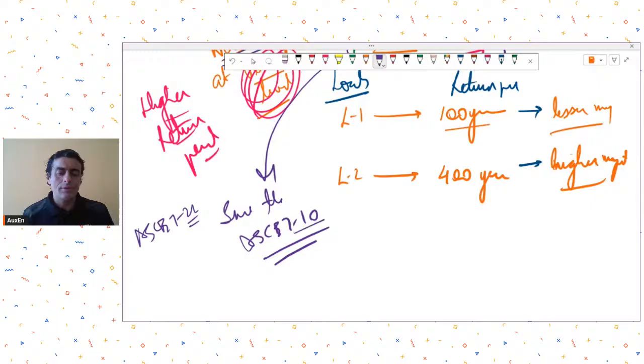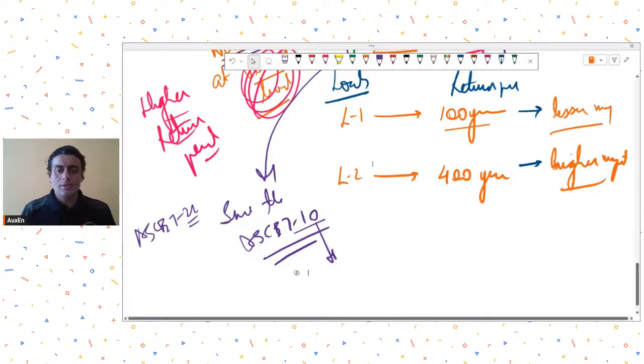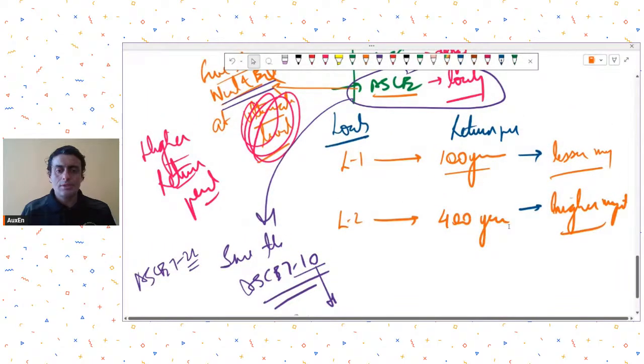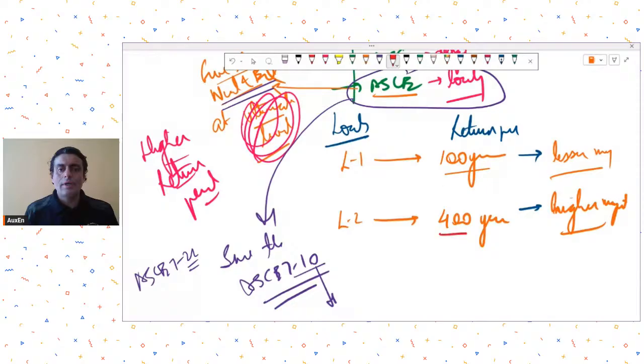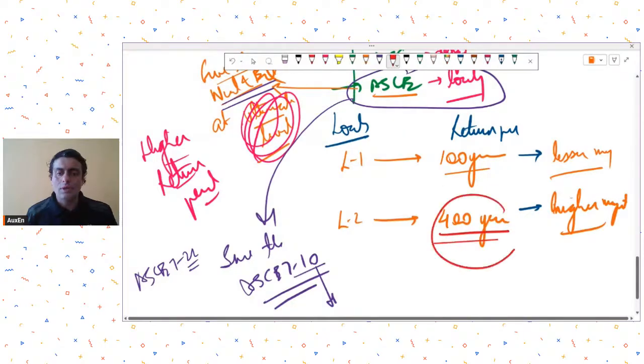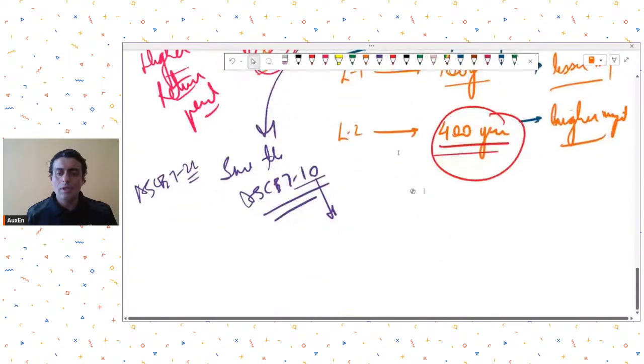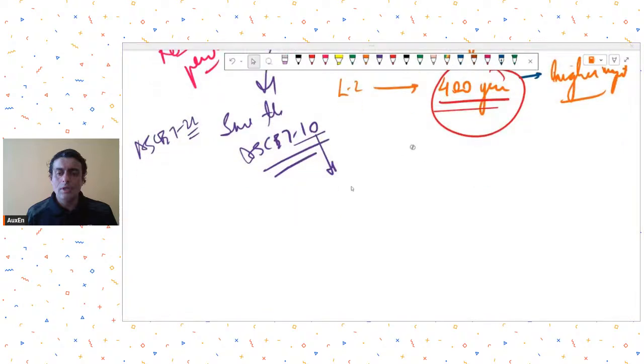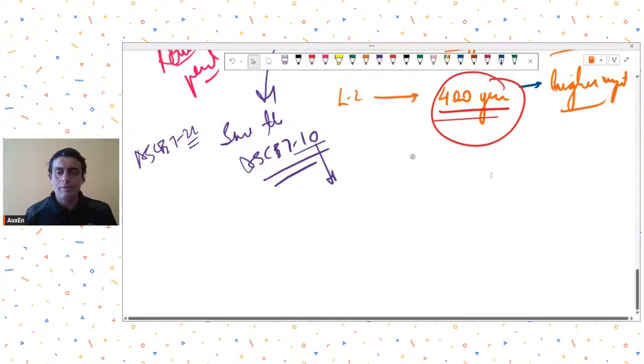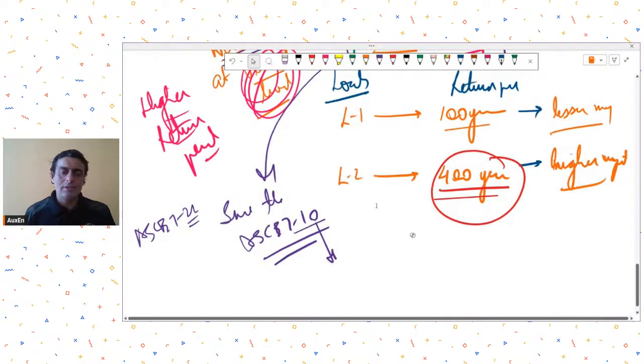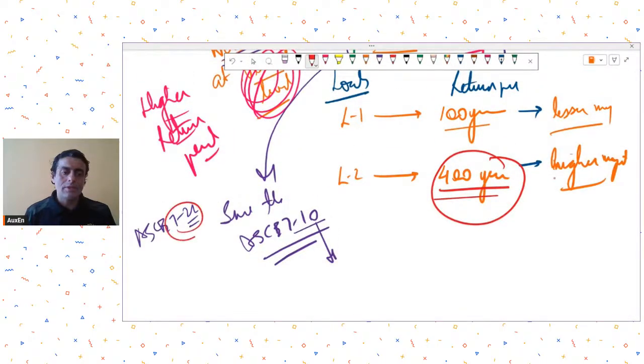So since the ASCE 7-2010 version, they have sort of made the return periods higher. So now the wind and seismic return periods have been readjusted to higher-level magnitudes. Since the return periods have been adjusted to a higher value, the magnitudes of wind and seismic that you now get from ASCE 7-22, let's say, are greater than what you would get from the ASCE 7 before 2010.